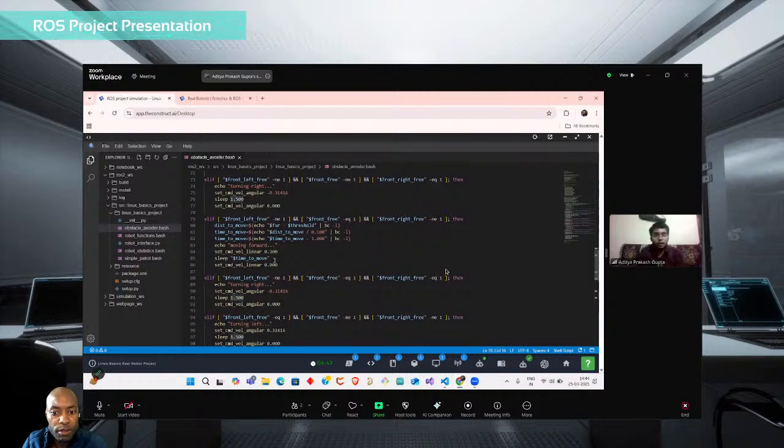Now for moving forward, I am calculating the distance to move. I am calculating the FSR minus threshold, which is how much it is free to move. For example, if the ball is way ahead, then the distance will be large, hence the robot will also move a large distance. So I am dividing FSR minus threshold by 0.1, which is my 0.1 meter per second linear velocity. I am just using the physical distance-speed-time formula, and I am calculating the time.